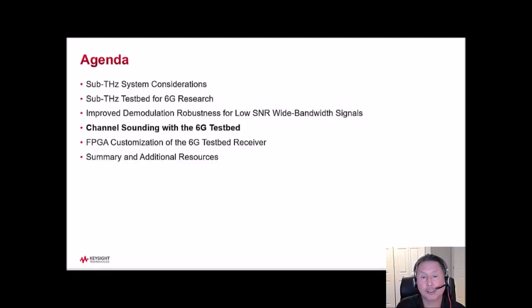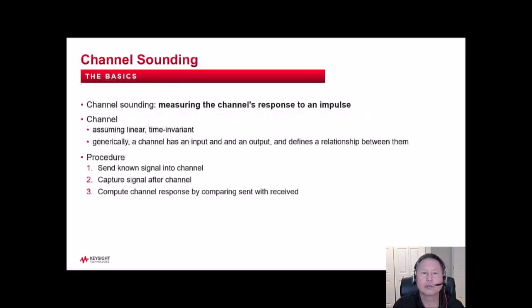The testbed can also be used for channel sounding, so next we'll discuss some recent channel sounding work that was done at D-band. Okay, let's first start with the basics. Channel sounding is the process of measuring the response of a channel to an impulse. When you know this information, assuming that your channel is linear and time invariant, you can predict what the response would be to any signal that you put into the channel.